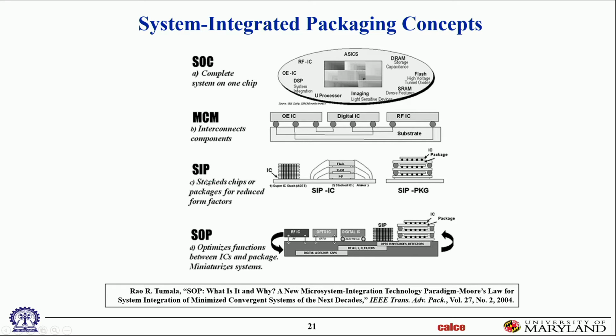And there are a little bit of subtle differences between system on a package versus system in a package. I'll come back to that later on. But the point of this slide is that the system complexity and the integration is growing radically, and how to package all of that in a way that they can electrically and mechanically function in a robust way is the challenge. And once again, everything you're doing here, silicon on chip, follows Moore's law. Everything you're doing outside of the chip is what industry calls More than Moore. So that's just a buzzword.